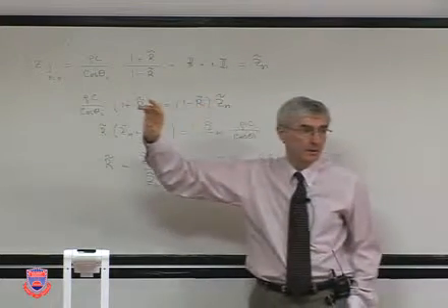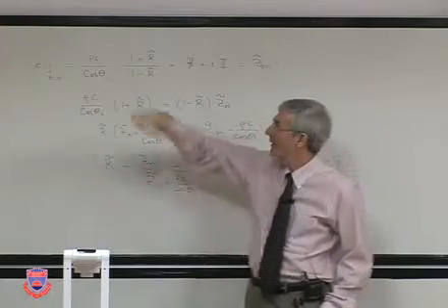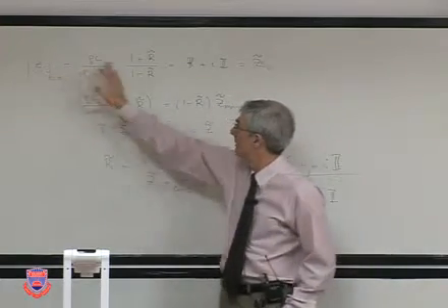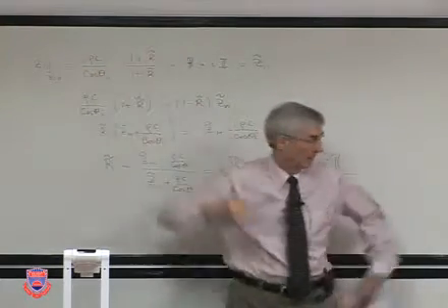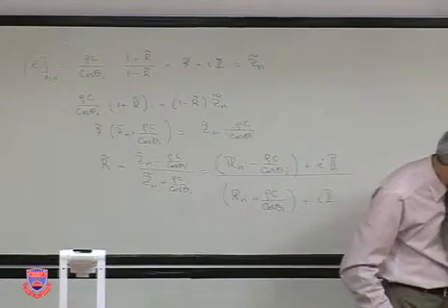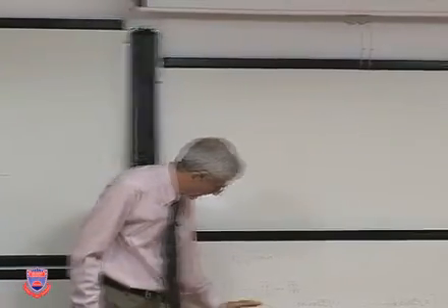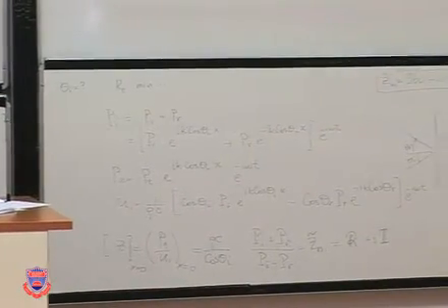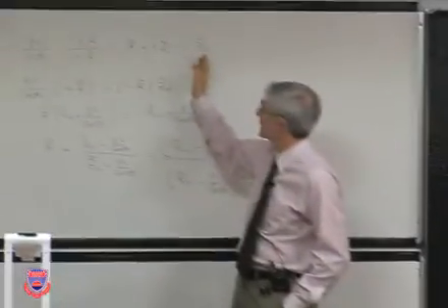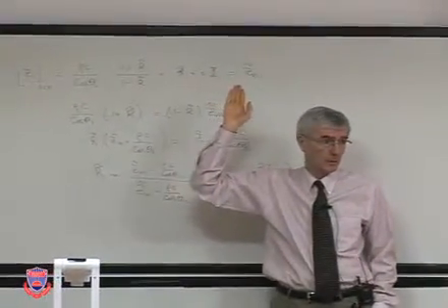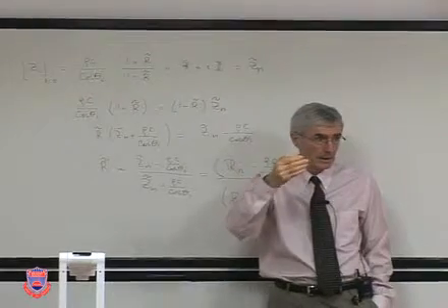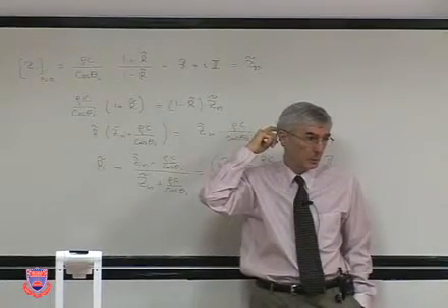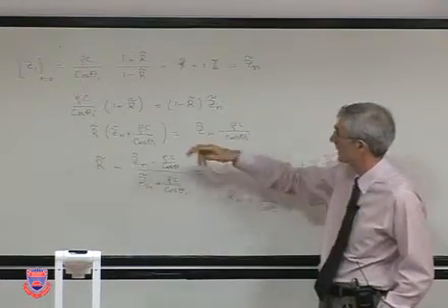What we did is we wrote the equation right here. Pressure field dividing, you have the impedance at x equals 0 at the surface. Okay? And then we say that must be equal to the impedance of the surface, because that's what causes the reflection, determines the reflection amplitude, and so on.